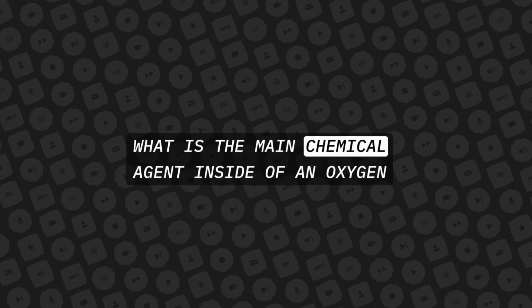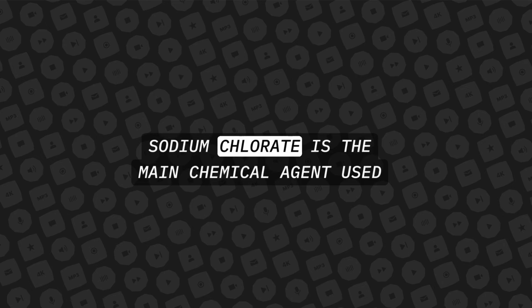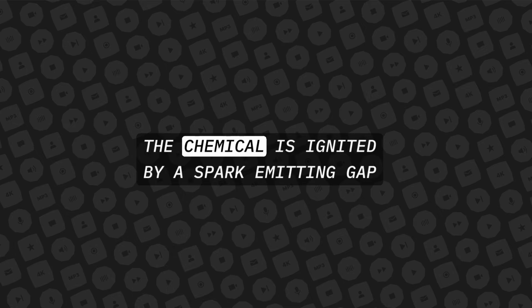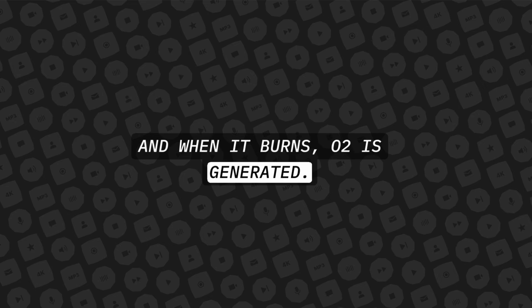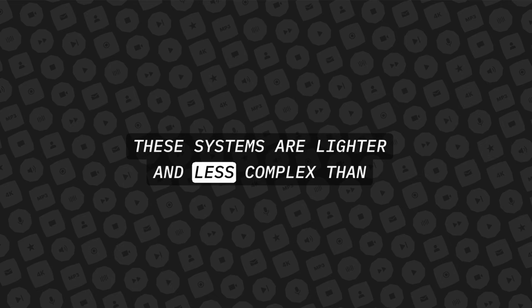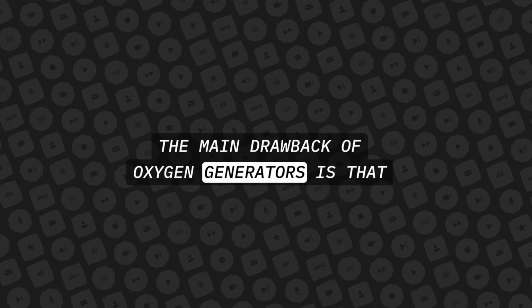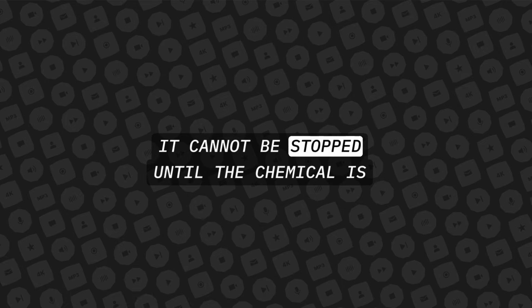What is the main chemical agent inside of an oxygen generator? Sodium chlorate is the main chemical agent used in aviation oxygen generators. The chemical is ignited by a spark-emitting gap, and when it burns, O2 is generated. These systems are lighter and less complex than oxygen storage-based systems. The main drawback of oxygen generators is that once the burning of the sodium chlorate begins, it cannot be stopped until the chemical is consumed.